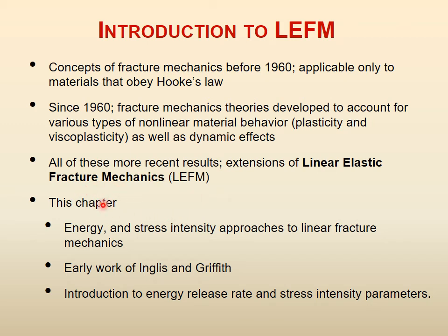So in this chapter, energy and stress intensity approaches, two different approaches. The same thing is happening. You are applying stresses, and these stresses, because there are flaws or defects in the material, are having stress concentrations. But the way you look at it mathematically or mechanistically is you find the changes that are happening in the energy or stored energy or work done on the material, or changes in the stress intensity. So we will see these two approaches to linear fracture mechanics.